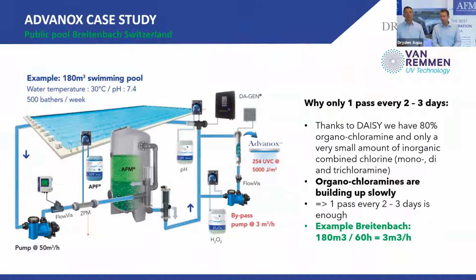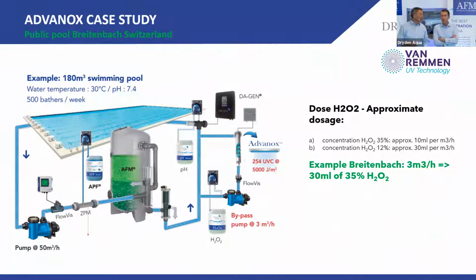Organochloramines are building up slowly. Every 2 to 3 days is enough. And the dosage of peroxide? That depends a little bit on the concentration of the peroxide, right? I think here in Switzerland, we still have 35% concentration.